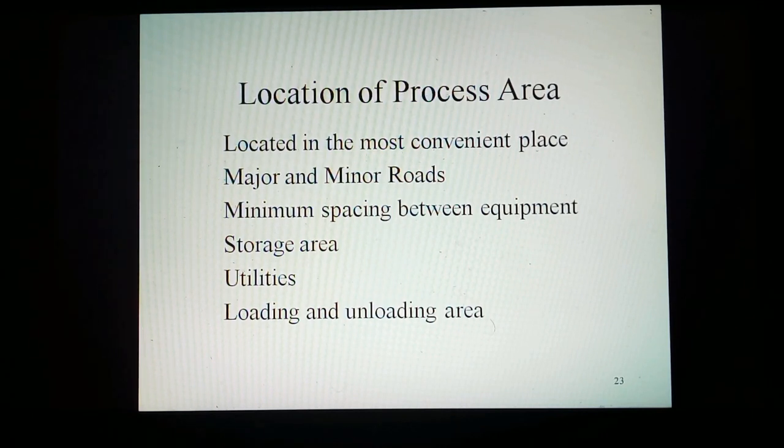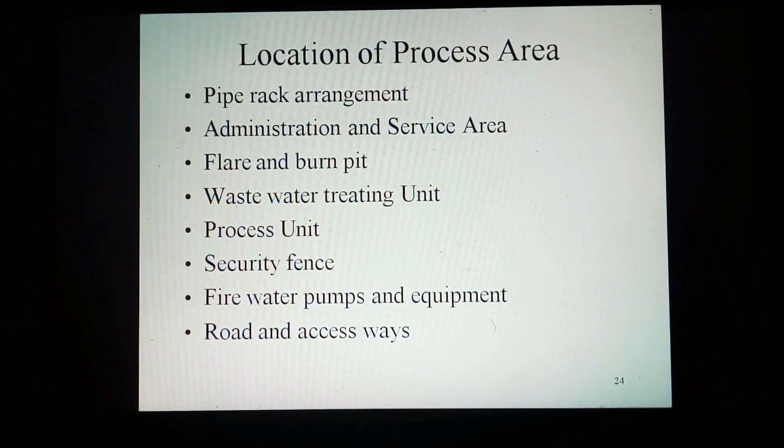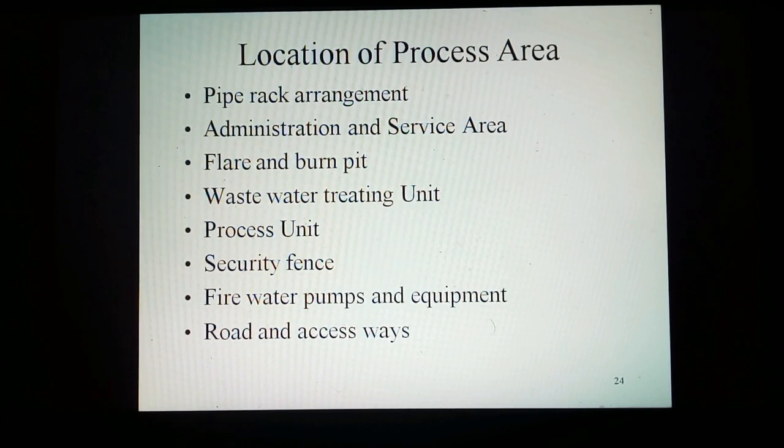Loading/unloading areas for road transport shall have adequate space to provide access for filling, parking and maneuvering. The drive-through rack arrangement is preferred. The loading and unloading facilities should be downwind or crosswind from process units and sources of ignition, based on the direction of prevailing wind. For marine transportation, the area shall be located on the seaside or riverside in the plant site.